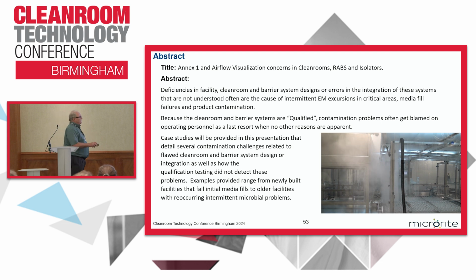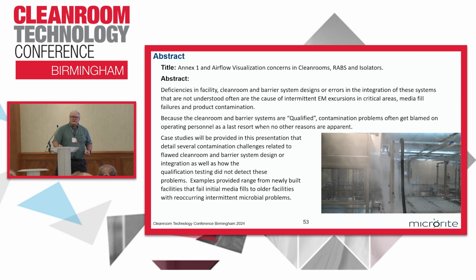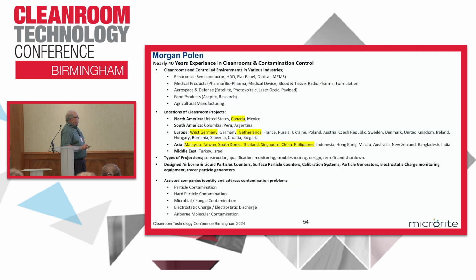We uncovered this. This facility had been in operation for 6 years. They called us in a panic and had me fly down to Buenos Aires to do a smoke study because the FDA was coming within a month. They had been operating all this time without any smoke studies. What we found was this error, and there's actually a HEPA filter above here that their own building automation system had pointed out had been off for over 2 years. People lost jobs, management changed, and the facility had to move on.